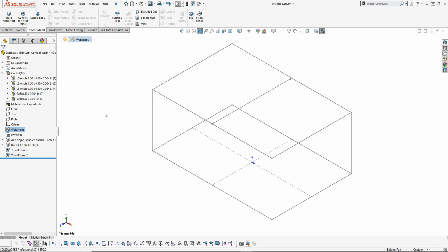All right, so for the first piece of sheet metal, we're just going to use the right plane, and I will add one to the back. I can also go into the 3D sketch and create what we call the dreaded sketch plane, which inserts a plane into a 3D sketch and is a little more difficult to use, but can be handy, but certainly not the first choice.